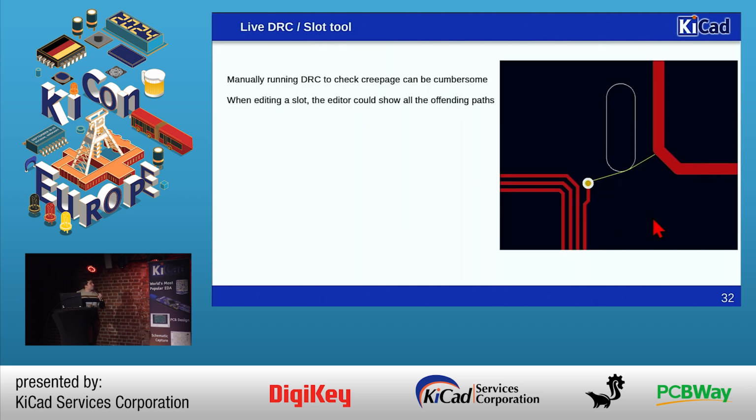Another tool that we could do is a live DRC. That would be great, and this is what it could look like, basically showing the paths that do not comply with the creepage rule. For this instance, when you increase the length of the slot, we see the path moving, the path changing, and at some point it completely disappears because it is then within requirements.